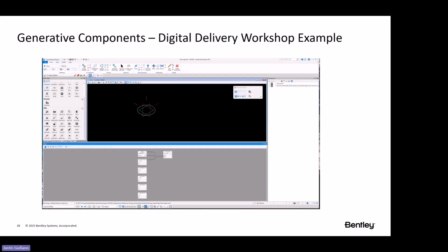All right, so here is where we have a graph with the value nodes feeding into the circle node. So what we did is we just clicked on our circle node over here, dragged it over, and in there we have different arguments that we need to satisfy in order to build that object. And we'll see that on the next slide here as I go. But basically what we need to do is identify a technique, so how the circle is going to be built. And then each technique is going to have different arguments that we need to satisfy. So let's see what that looks like.